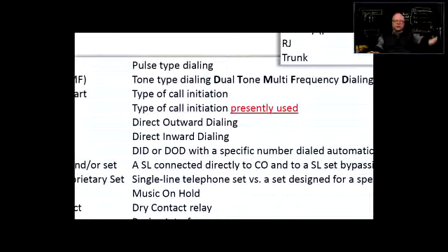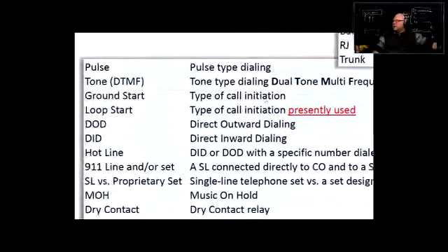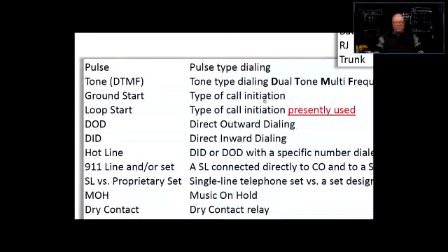When the circuitry senses those two tones present at the same time, it is going to receive it as a number was pressed. If there were no two tones associated with that, some noise, a car driving by or some TV playing, could actually trigger the circuitry to think that some number was pressed. Right? So that's why.